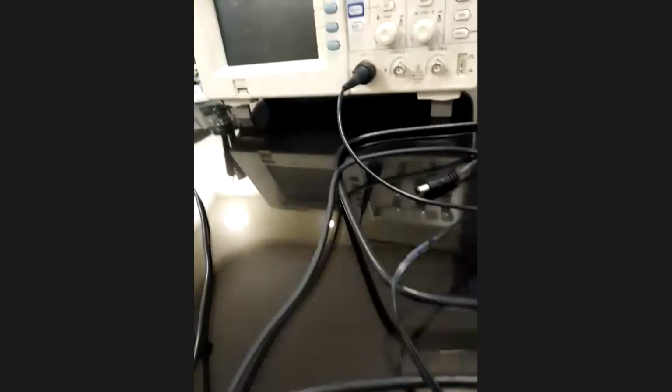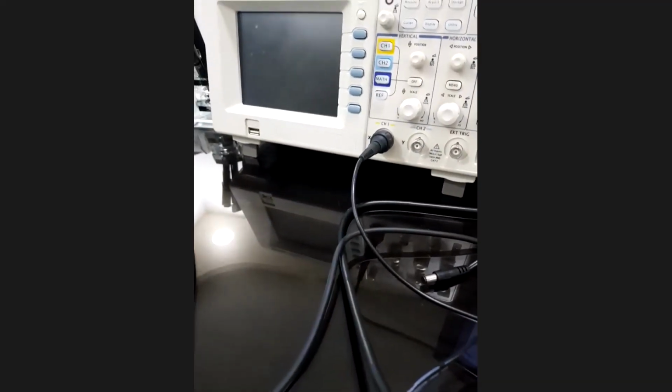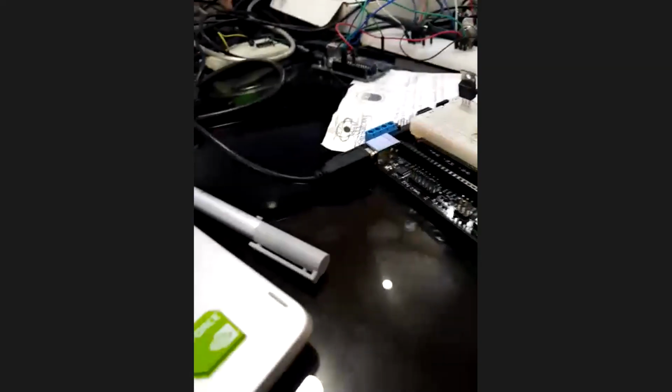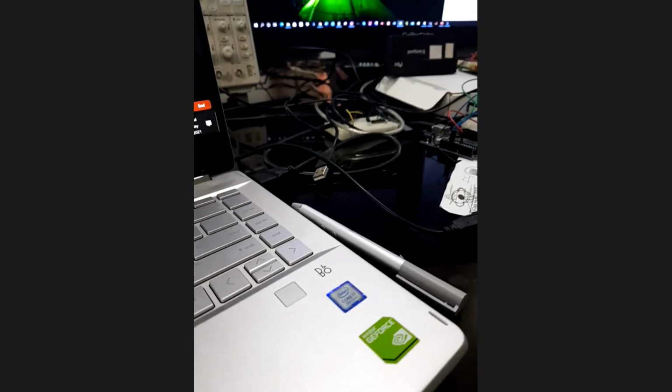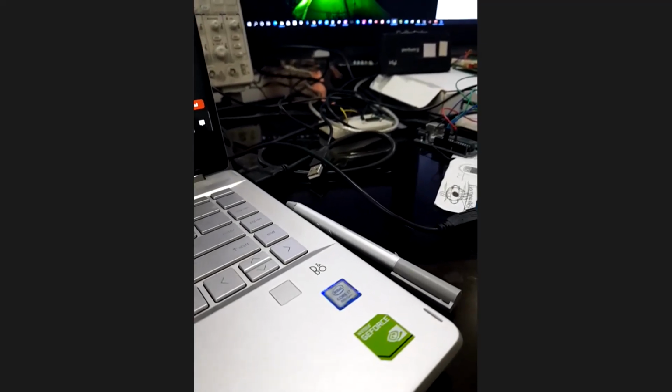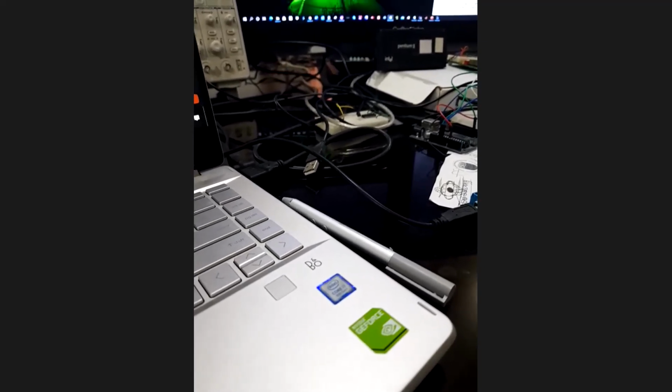You know what I do, Mustafa? I use this guy. This is my favorite friend. Oscilloscope. To know how much time a piece of code takes, just raise a bit before that piece of code, remove the bit, then lower it and put it on the scope. So you can know exactly how much time every piece takes. Yeah, you can see it as a square wave on your scope.